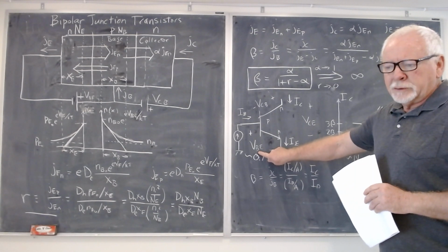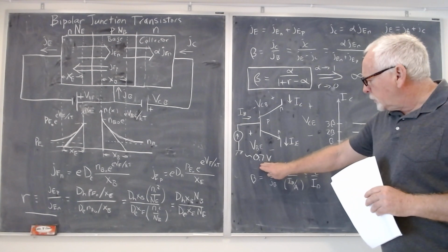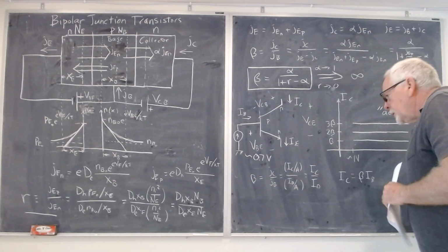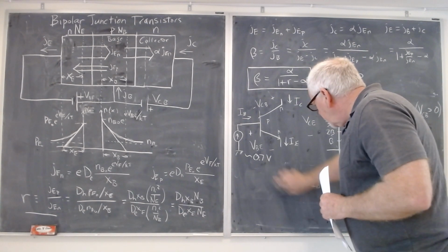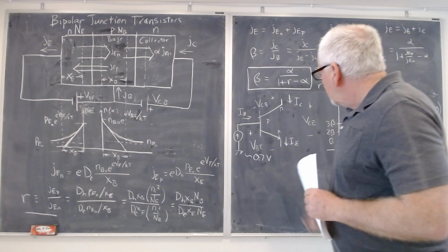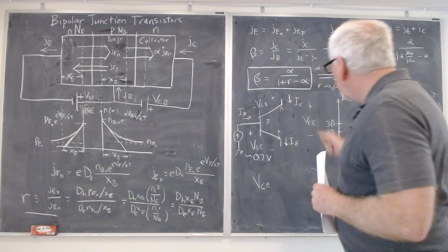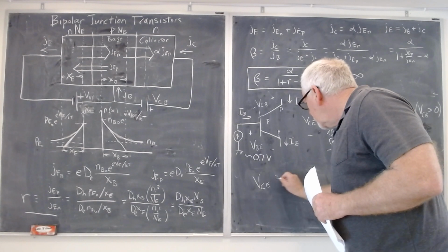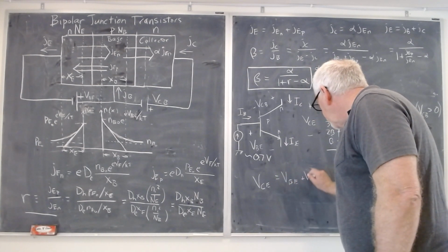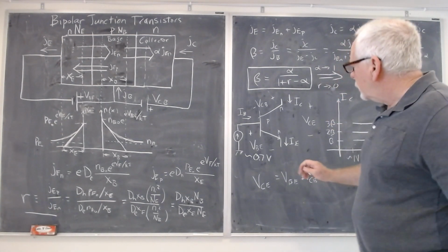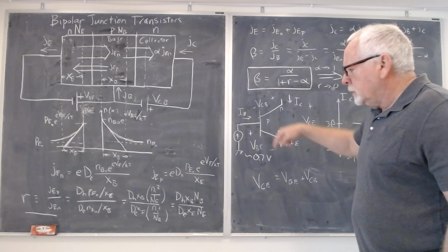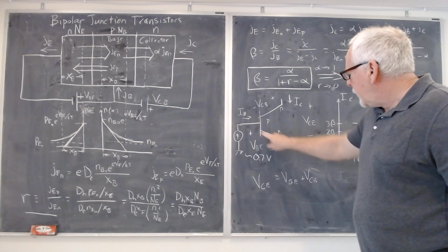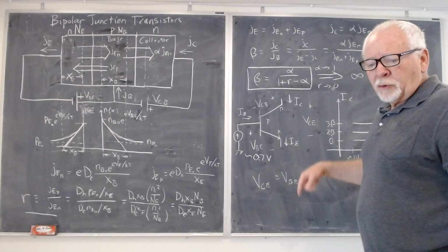The base emitter transistor junction remains forward biased, and so as you know, to a forward biased diode, you need a voltage of around 0.7 volts. And so what happens is that if you look at the schematic, you can see here that VCE, the voltage of the collector to the emitter, is the sum of these two voltages. Minus plus, minus plus. And if you look at how we've drawn them, of course VBE is always positive for forward bias because we're doing NPN, and so that's the voltage of the P base to the N emitter. And remember your mnemonic: forward bias, positive P side.